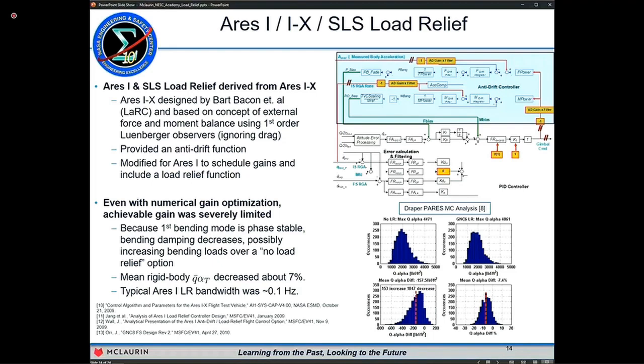So what we found is that if you have reasonable accuracy GPS INS on the vehicle, and combine that with good day-of-launch measurements, either from balloons or radar, it's possible to construct a synthetic angle of attack estimate that's of very, very good quality. So we have access to inertial air data, and in the interest of time, I'll speed up just a little bit here. This is actually a nice high fidelity simulation, and for various reasons I can't include the details on the INS, but this is a medium tactical grade IMU with GPS aiding,